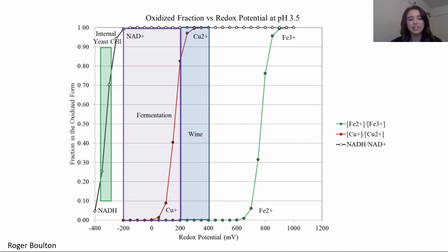But like I said earlier, here we see this variable, redox potential, that's changing drastically during the course of fermentation. And it's not being monitored or controlled. We monitor and adjust pH, we monitor and adjust temperature. And here we have another opportunity for better control over the fermentation by using redox.